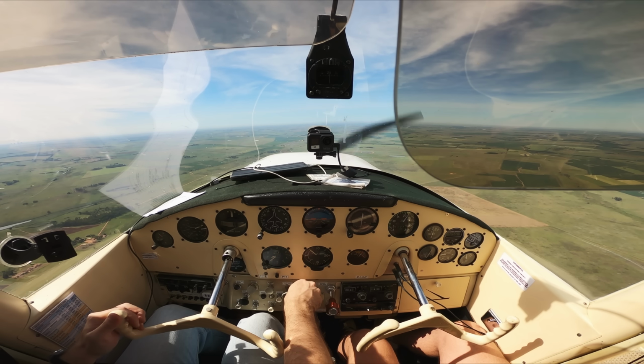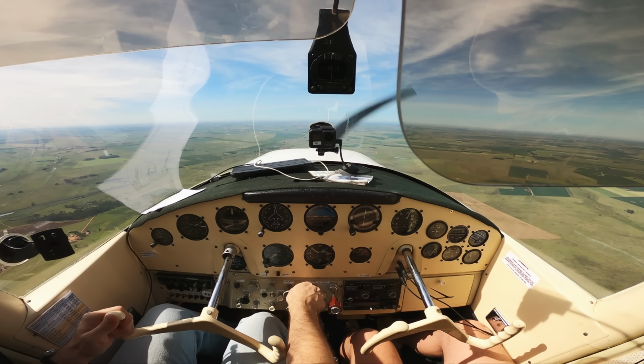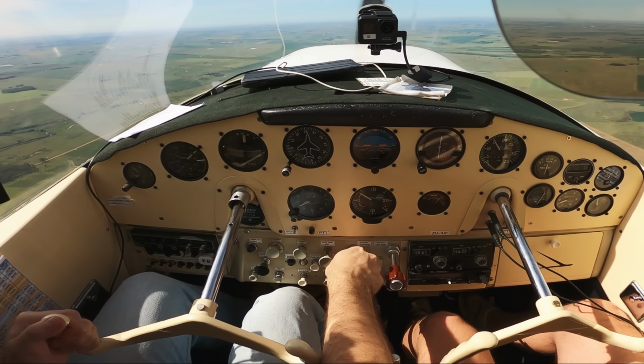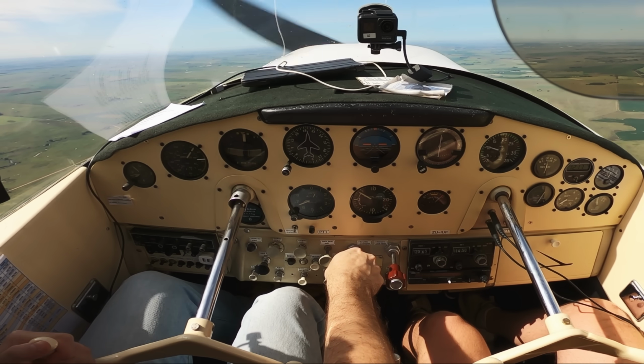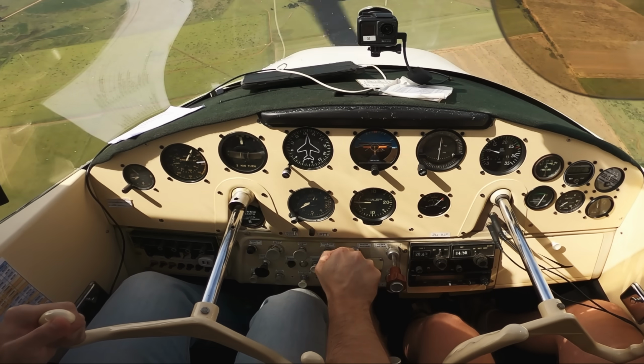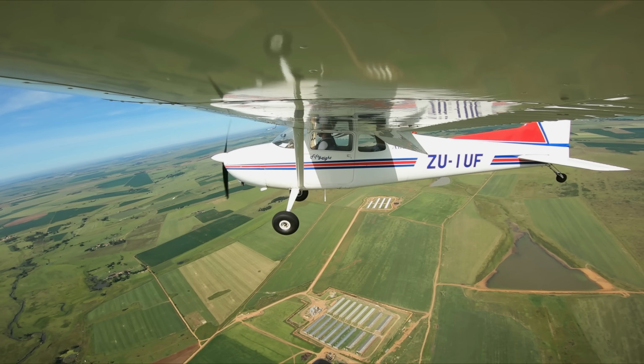Next time you go out for stall recovery practice, bring along a proficient rated pilot or flight instructor. Let the instructor perform some stalls while you closely watch the yoke or stick. You'll notice that the stall only occurs when the control is pulled fully aft or very close to it every single time. Interesting, isn't it?